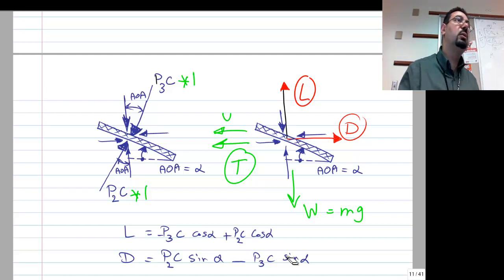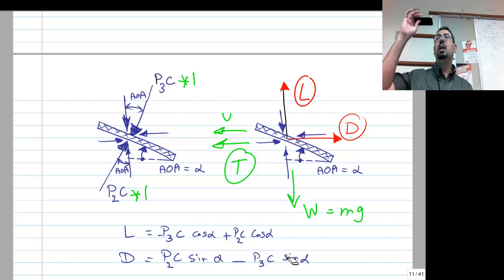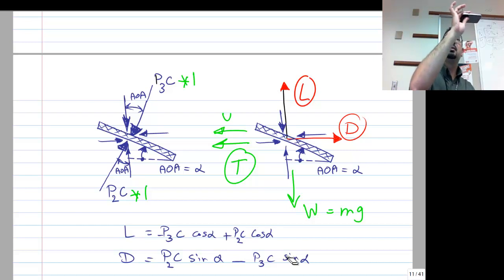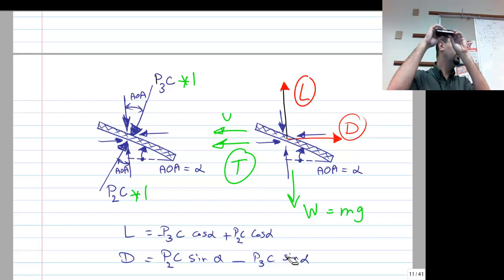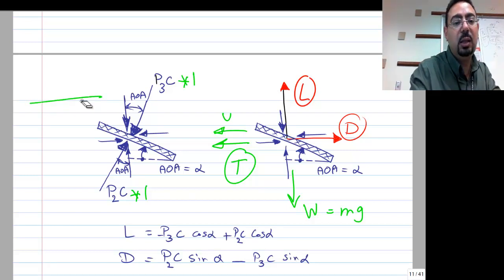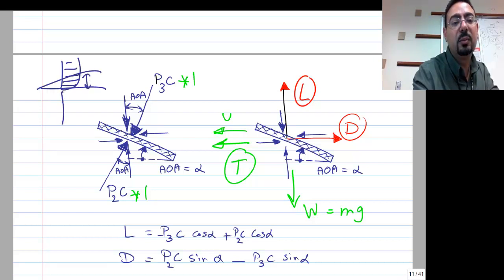So is there any other drag besides the pressure drag? Yes, friction drag. You can imagine if that plate moves like this, you probably will not have much pressure difference on top and the bottom. They will be the same. So does that mean it can fly supersonically without any resistance because the pressure is equal? No, there is skin friction drag. Where is the skin friction drag? If I plot my plate flying horizontally, there will be something called the boundary layer. It's in that region. It's very small, a few millimeters.